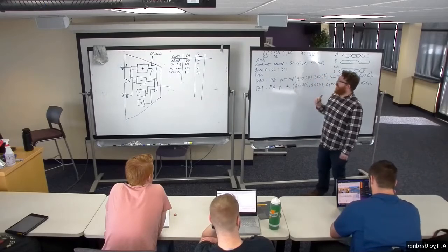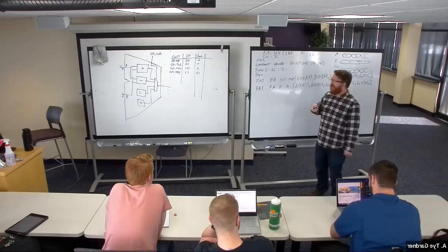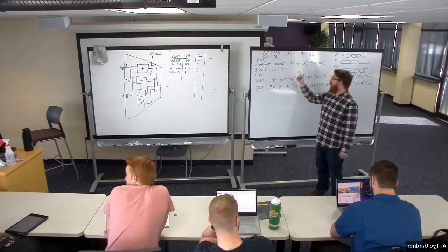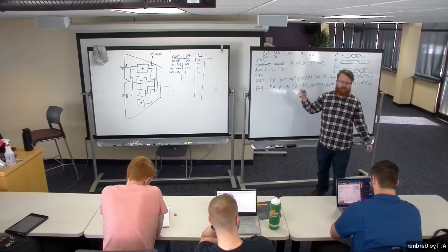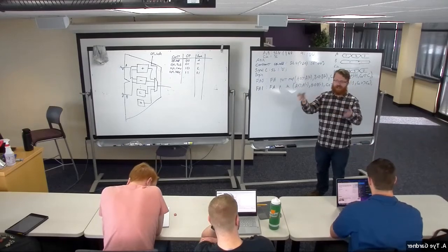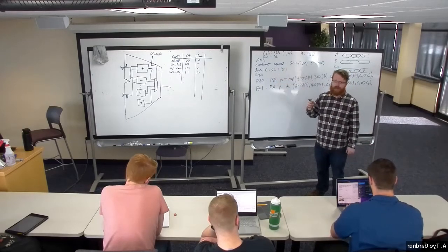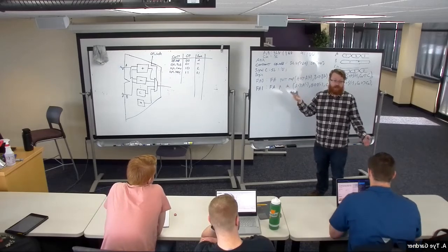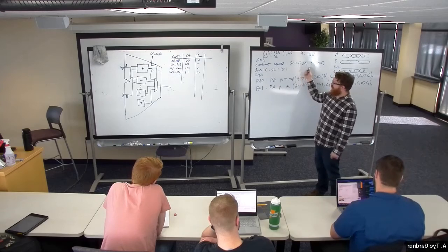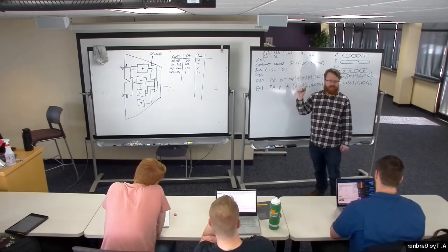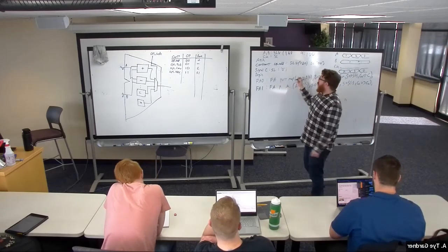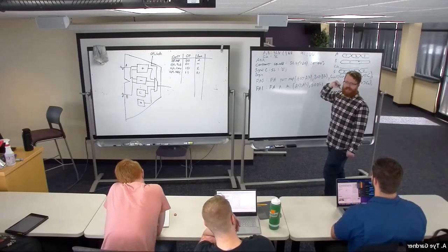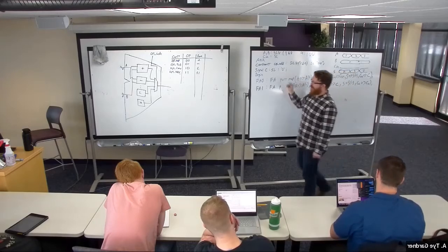Constants, however, function a little bit differently in that since it doesn't have to carry a value with it anywhere, it doesn't have to change, it just loads this value into a memory location. It says, put it here, and anytime I want that value or give it the word op add, it goes and looks up what are the contents of that memory location, and that never changes. So that's why it works for constants and doesn't really for signals. So just be aware. This initial value statement, save it for constants. Stay away from signals.